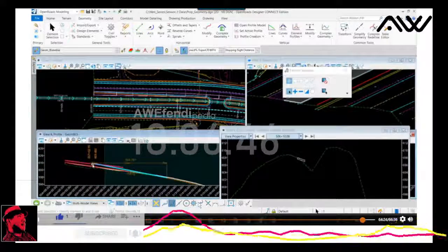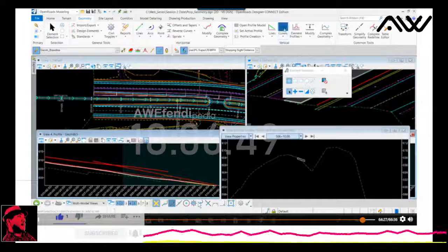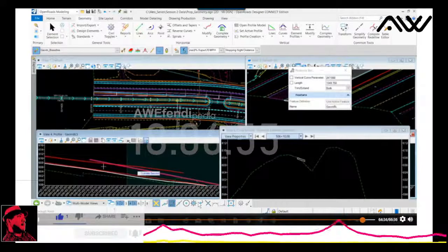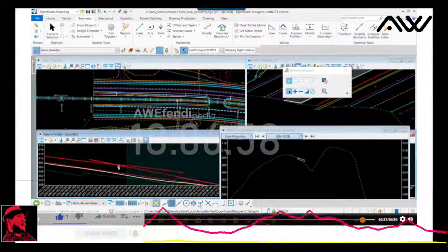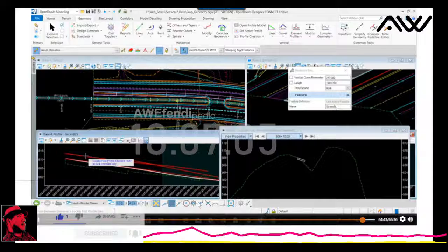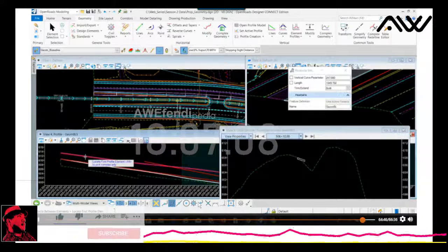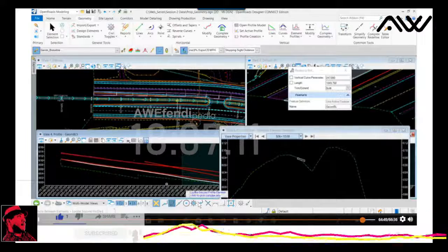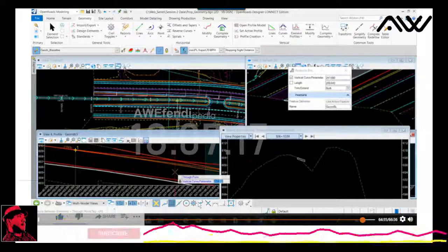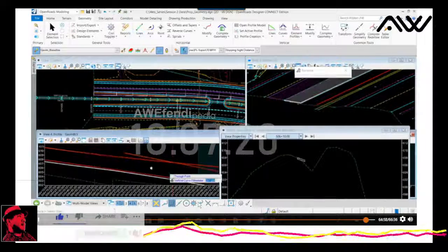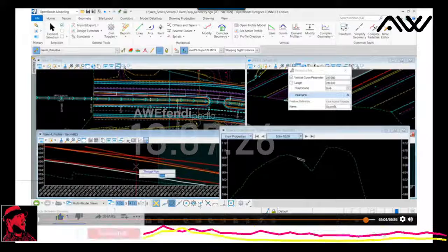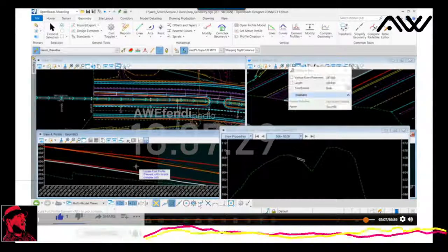And I'm going to just insert another curve between my elements. So as I zoom in, bear with me, I'll select each element. Let's back out, make sure I've got that. I want to be sure and select the geometric element and place that arc. Be sure you select the geometry that you created, not the graphical representation of the pavement. Now at this point, my K value is at 247. It's locked based off the design standard I have placed, or I have told it. So I'll data point through the prompts, and now I have that vertical control line in place.